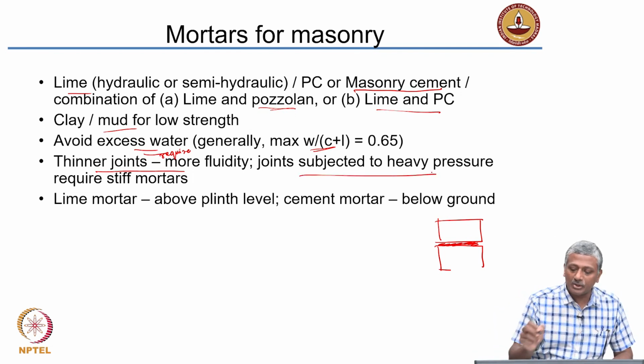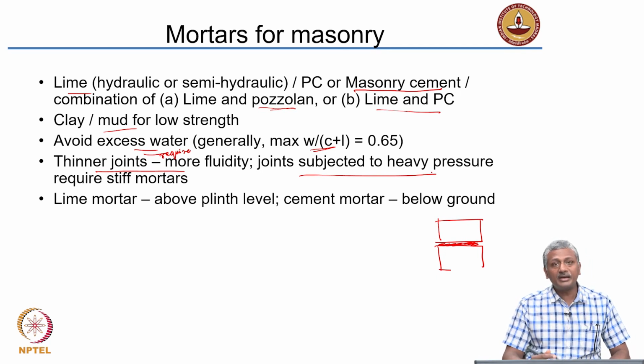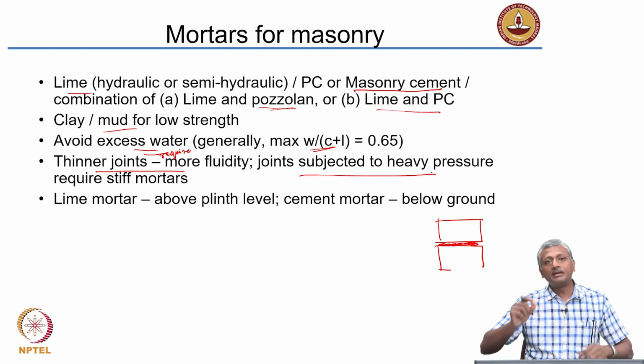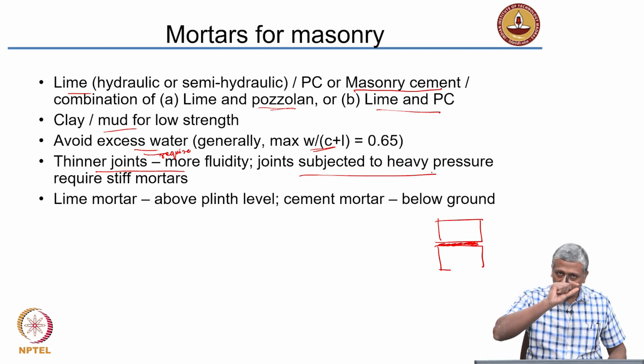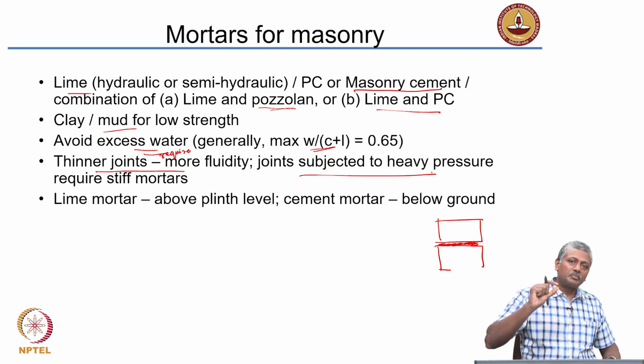But joints that are subjected to heavy pressure require stiff mortars. So if you're, for example, very heavy loads are coming, the mortar itself should be designed in such a way that even if the joint itself is thin, the mortar should become stiff to ensure that it does not deform